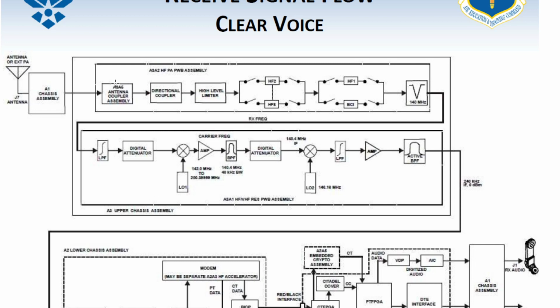What did the directional coupler do? It passed what to the antenna coupler? What kind of data? VSWR. The VSWR data, the voltage standing wave ratio data. Do you think that's going to change its job on receive? No, sir, it's not. Nothing is going to change its job when we come back through on the receive side. We just added a couple small things, and there's some things that are reversed, and that's what we're going to go through in these next couple slides here.